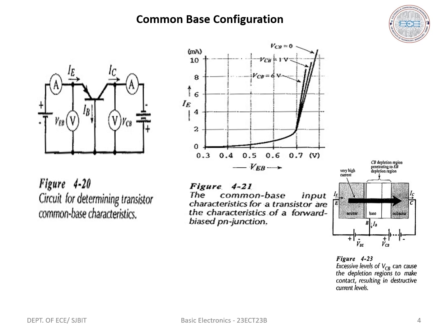Next, we have the input characteristics of a transistor. The input characteristics is always a graph of input current versus input voltage. For the CB configuration, the input current is the emitter current and the input voltage is the emitter to base voltage. The input characteristics is plotted at a constant output voltage VCB.